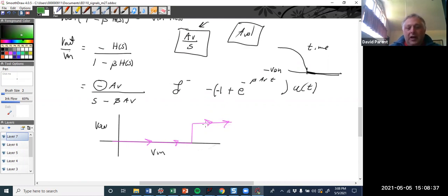But if I start high and go low, this is my direction. And what that's saying is if V out is low and you go past this threshold, the output goes high. But then if you're bouncing around, it won't go low until it goes past that other threshold. So it gets rid of noise.